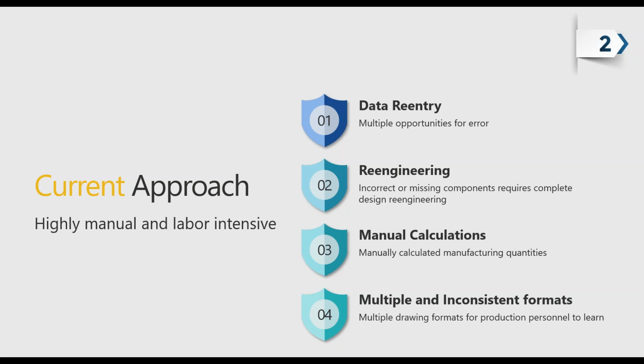Design engineers are mainly concerned with the electrical connectivity of the system, not the physical aspects of the harness. Often, they are not knowledgeable enough about harness components, and it is then up to the harness supplier to essentially re-engineer the harness to make sure that the correct components are used and are accounted for. The last thing you want is to be in the middle of the first production run and find out that the chosen terminal does not fit the wire.